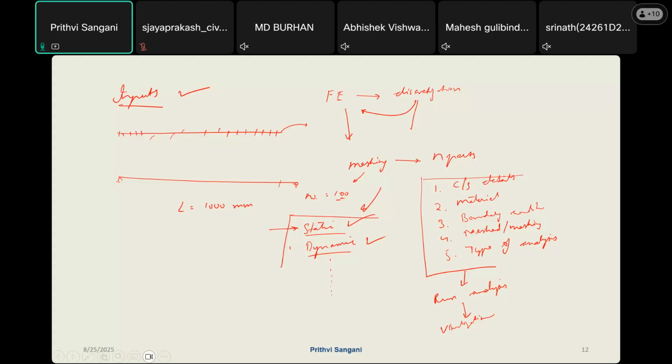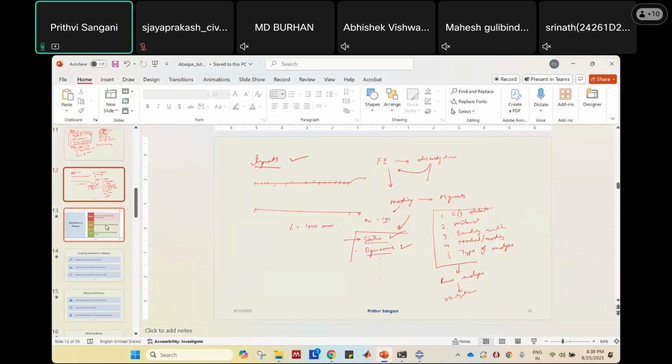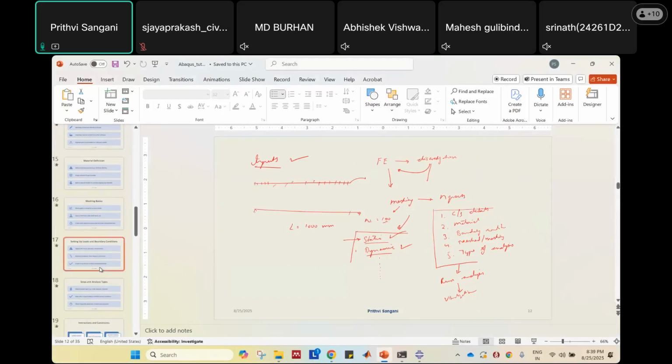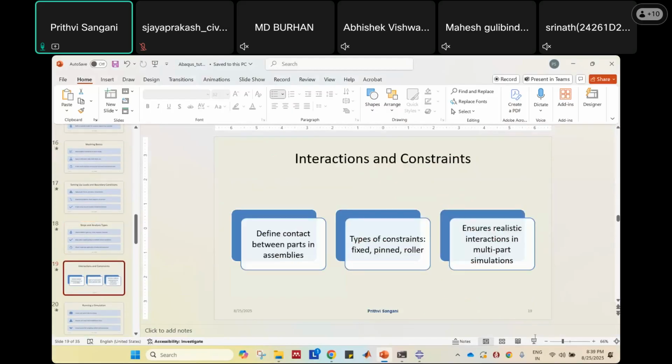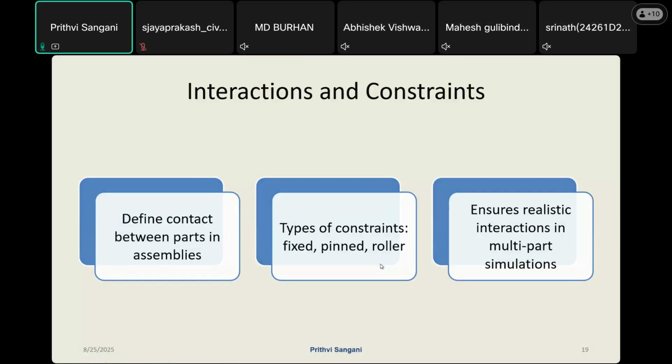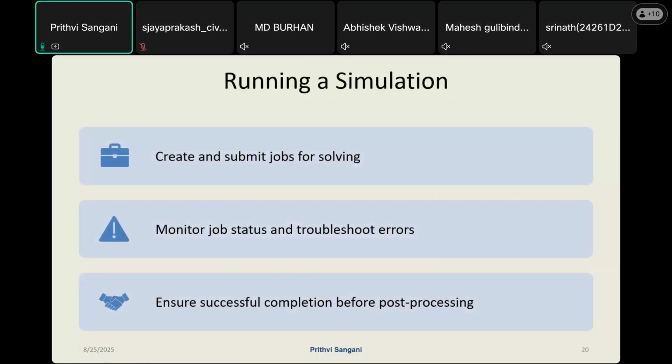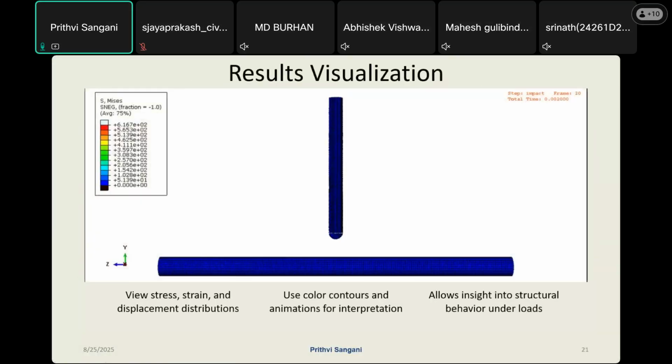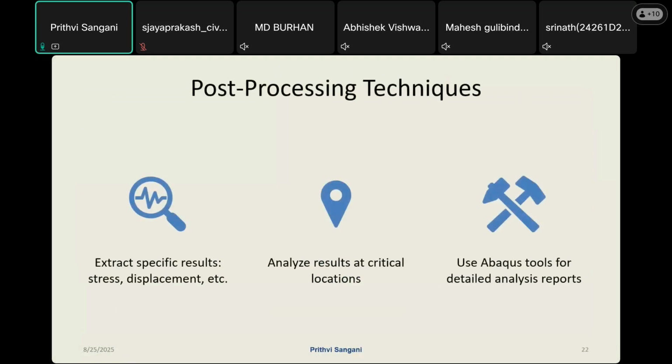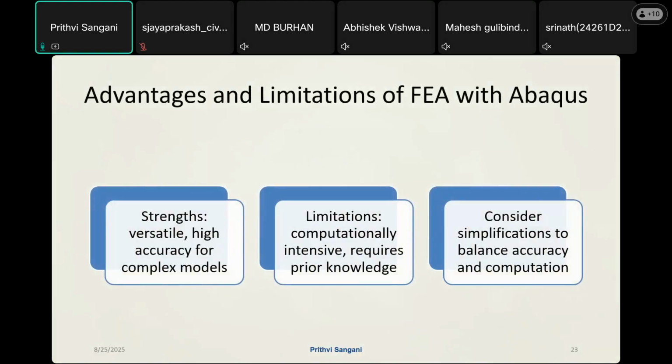So this actually requires very prior knowledge of inputs. And inputs definitely means your finite elements. You should also have some knowledge of your finite element schemes and even meshing. See, meshing is a part of finite elements. So how do we find out the optimal mesh size? We can do a mesh convergence, which again I'll discuss when we are doing the hands-on training.